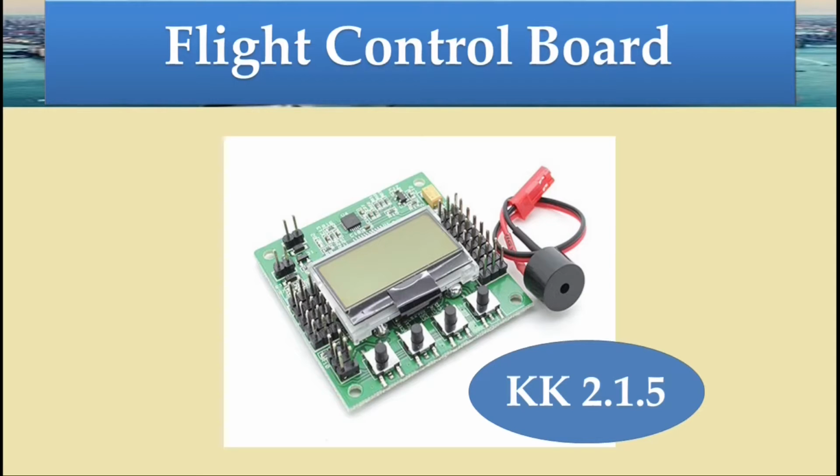This controller gives us 8 PWM outputs for motors and 5 inputs for remote receiver. It takes 1520 microseconds to detect input and 1520 microseconds to give output response. It has on-board battery voltage monitor, and also there is small indicator and speaker available for any type of indication. You can configure this by using display which is on the board and 4 keys which are available on the board. You don't need to connect this with any PC or laptop.